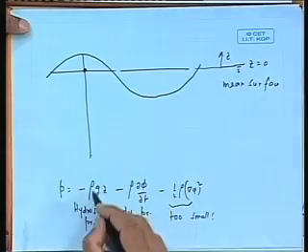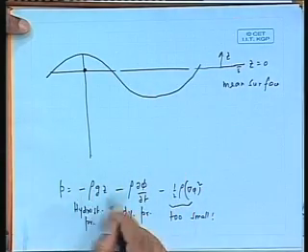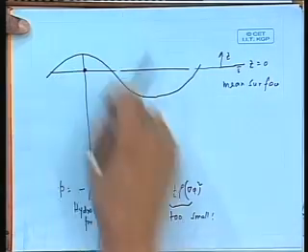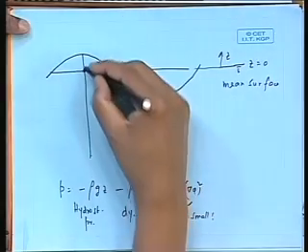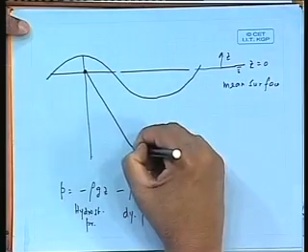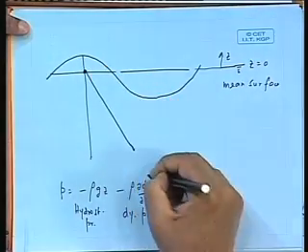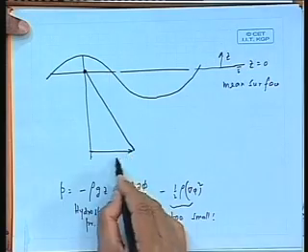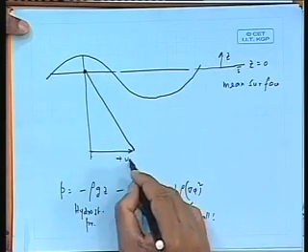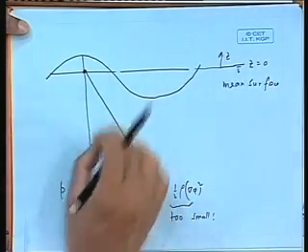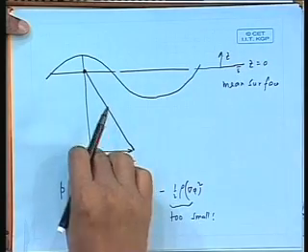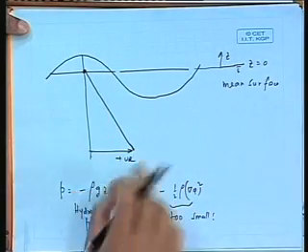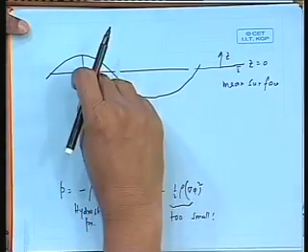Okay, I am looking at this pressure. Let me see how this pressure looks like. See, this water pressure, how will it look like with respect to depth? Obviously, it will go down like this, because it is 0 here and it will go down like that. See, as z is negative, these are all positive values, this is positive pressure. Suppose you take z is minus 5 meter, obviously it will be minus rho into g into minus 5, rho g times 5 pressure. As z equal to 0, it is here.